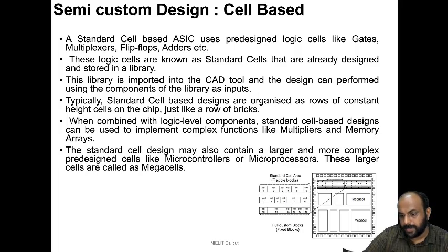So there will be mega cells and micro cells. Mega cells are nothing but larger and more complex pre-designed cells, whereas standard cells are not that complex but predefined cells which are basically imported to the CAD tool. They are made available by the fab and imported to the CAD tool for performing semi-custom cell-based design.